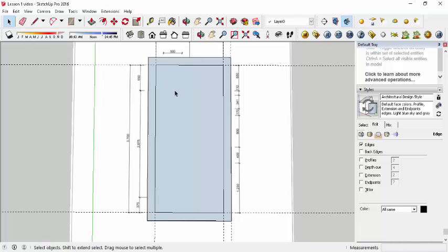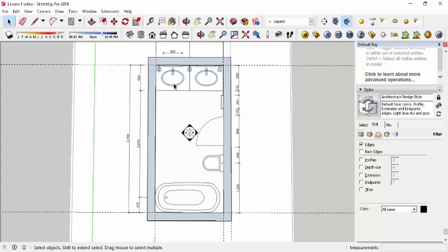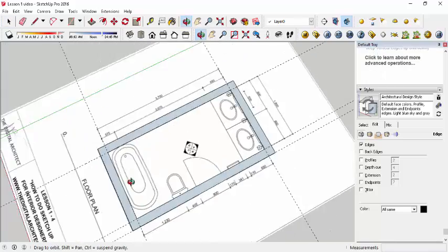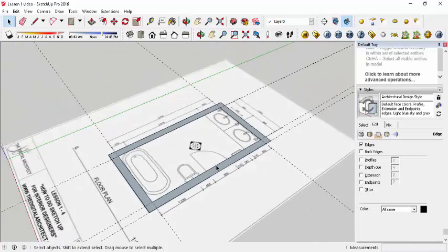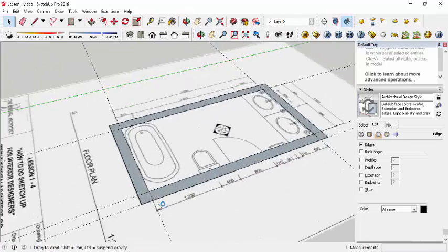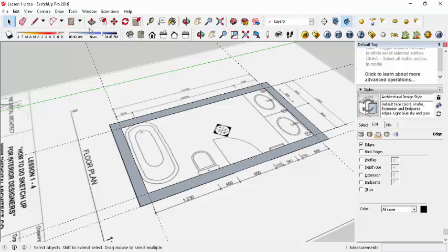We're doing the wall now, so I will click the inside rectangle and delete this one first. Now that we have the wall, it's still in 2D, two-dimensional. We want it to be in 3D. For us to do that, we will use the push and pull tool. Click this or type P on your keyboard and then hover your mouse inside.